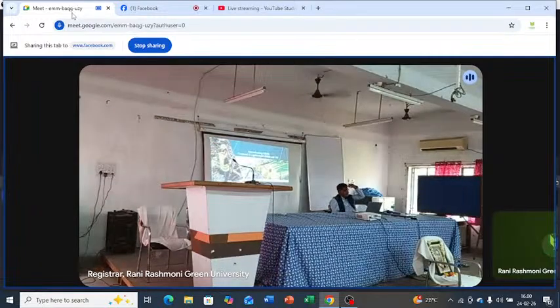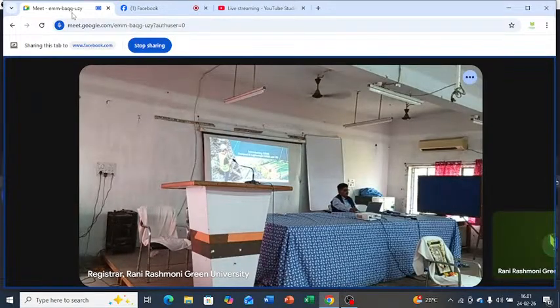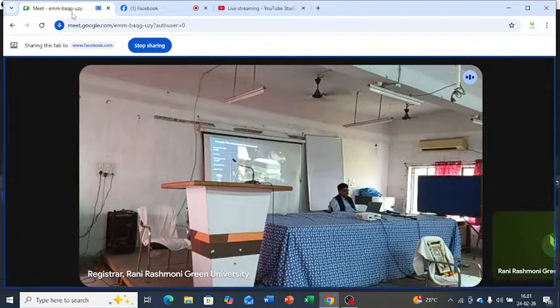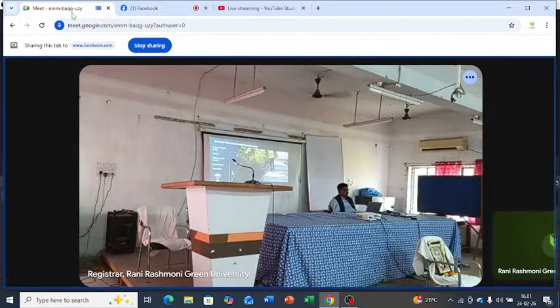Now coming to another piece of equipment which is slightly above this instrument. This is called GS05. It's a very small, portable and handy GNSS which gives you very high accuracy, and this also takes care of tilt. So very handy system. You can see how small it is. It can be held within a palm. And taking a point is just as easy. Put your pointing at the position, press one button and move forward.